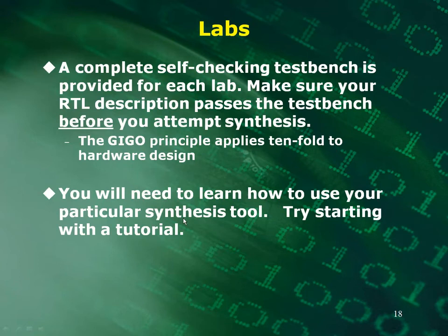I'll talk a little bit about the labs you're going to be doing for this lecture. There's a completed self-checking test bench provided for each of the labs. And I want you to make sure that your RTL description passes the test bench before you attempt to synthesize. The garbage in, garbage out principle applies much more when you're trying to actually produce hardware.